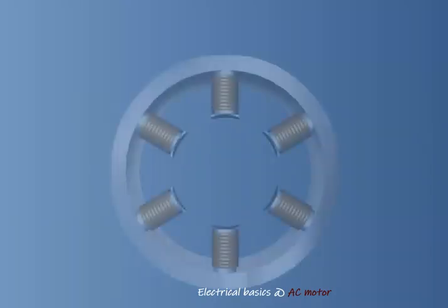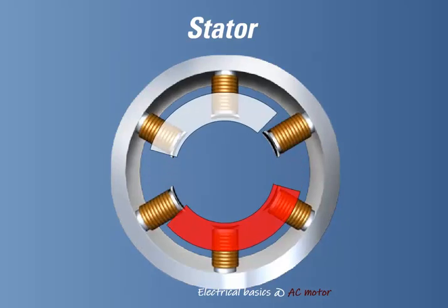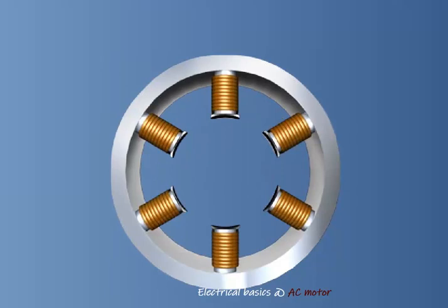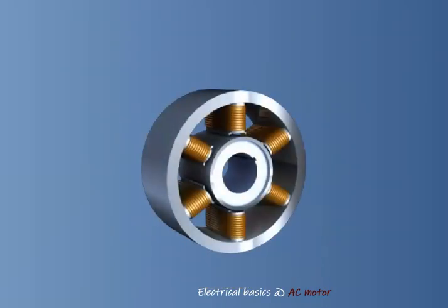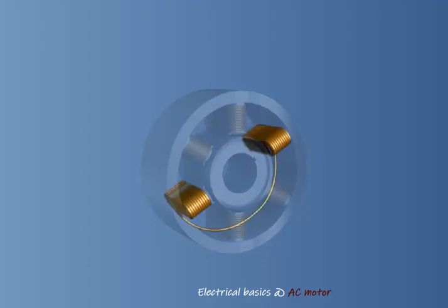The stator of an AC motor consists of a hollow cylinder with electromagnets forming the walls of the cylinder. These electromagnets remain stationary. The rotating field that they form when current is applied is referred to as the stator field. An illustration of how 6 electromagnets are wired and oriented to create the stator of a 2-pole AC motor is shown in this wiring diagram.